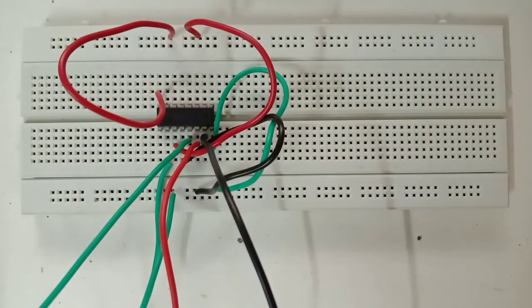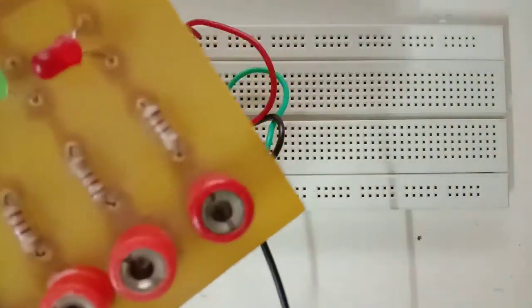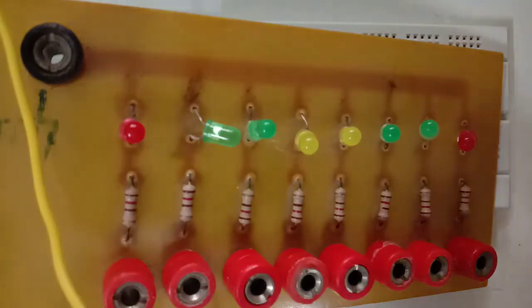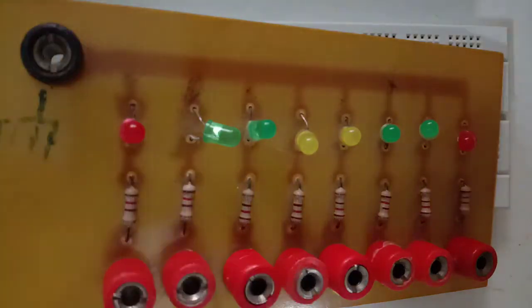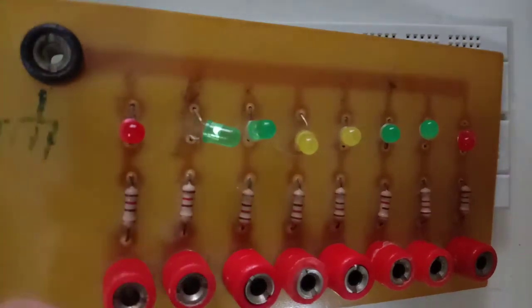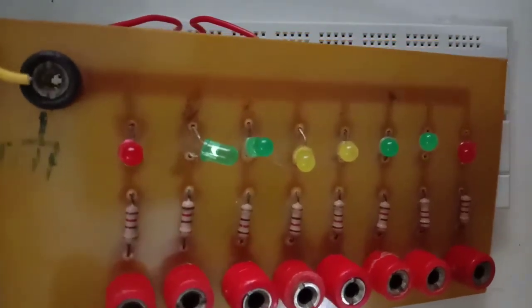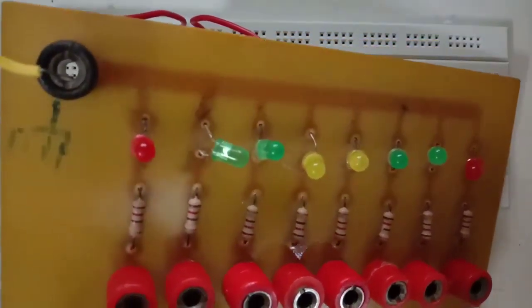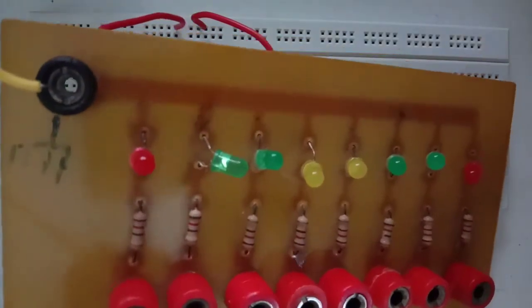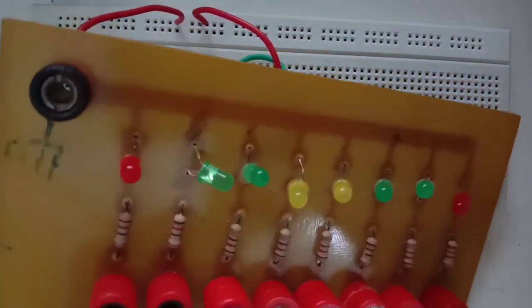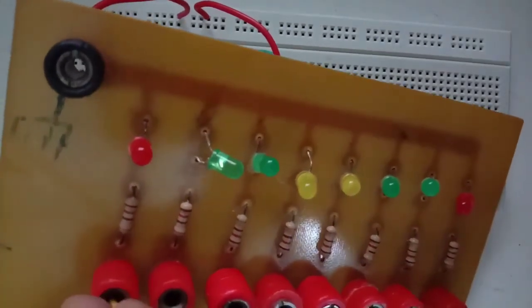Fine. Now our next task is to first verify the LED bank. How you can test it, I will show you. See now how you can test the LED bank. These are your power supply terminals: positive, a plus 5 volt DC supply is required, and one is ground. So ground is connected here and plus is connected here firstly. If the LED glows, in that case we can utilize it for your connection.